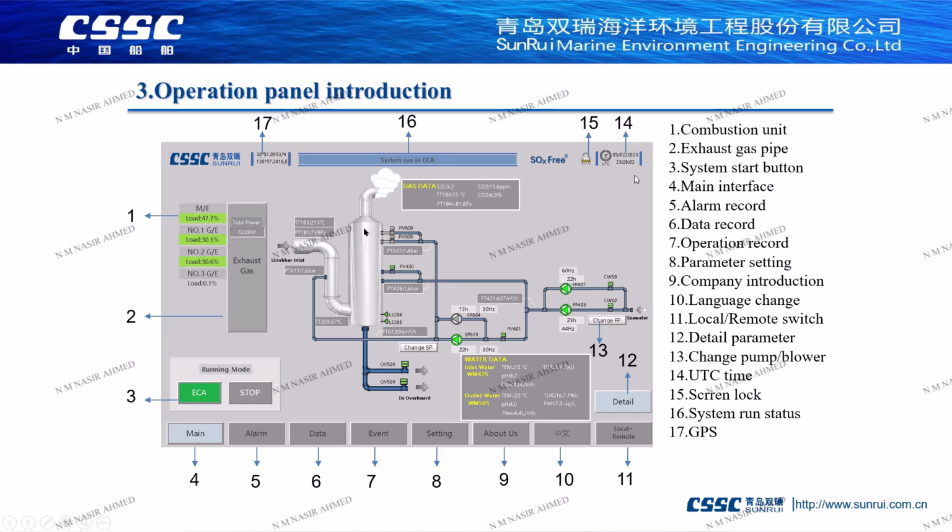The top of our desulfurization tower is equipped with a demister. When you start the system and when you stop the system, the valves on the upgoing lines of our pre-spray will open one by one to clean the top mist dispenser. Then the sprayed seawater is discharged overboard directly through the discharge line.